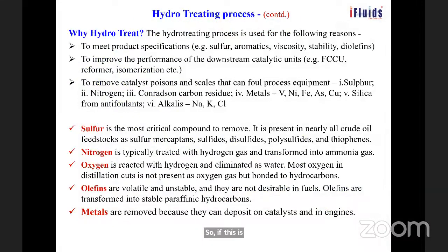Now we are coming to the hydrotreating process. Why do we have to do the treatment of hydrocarbon? This is basically because the hydrocarbons generally have a lot of sulfur plus nitrogen, aromatics, sodium, all those things, and the metals also, which I was mentioning yesterday, nickel and vanadium. These are actually the poisoning things for the catalyst, for the downstream units. So in the hydrotreater, all these things will be removed by injecting hydrogen at a high temperature in the reactor in the presence of catalyst. These things will be removed stepwise in the hydrotreater reactors. That is the main purpose of the hydrotreater.